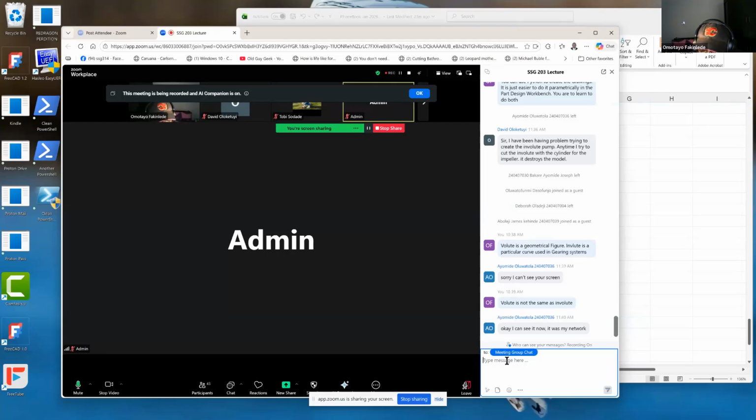When you edit the part file, everything will show in the component. You could even edit it on the system without even opening it, because each time your assembly will find where the file is located and it will update itself. If it doesn't update itself, you can tell it to recompute and it will update itself.